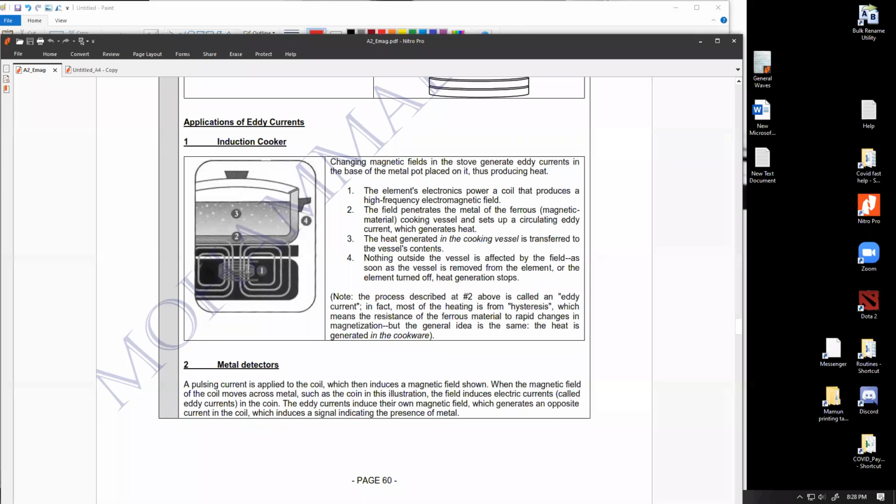So the direction of the current keeps changing here. This coil is fed with AC supply. So the closer part of the metal plate would be affected by a bigger variation of magnetic flux linkage. The radial parts or the distant part of the metal plate would be affected by a smaller variation of the magnetic flux linkage. So there would be higher EMF variation produced.